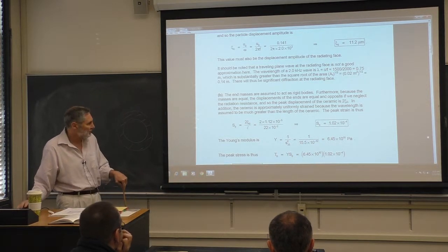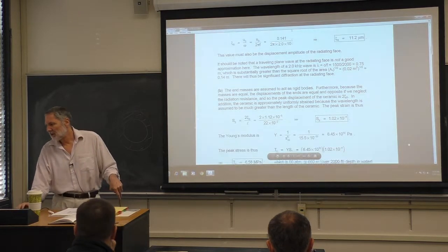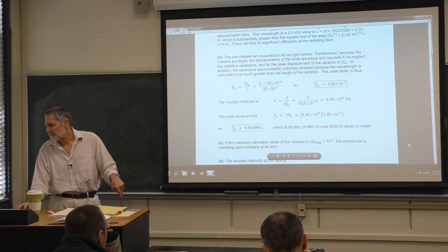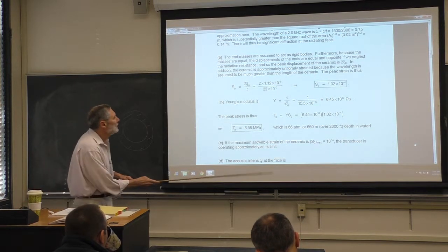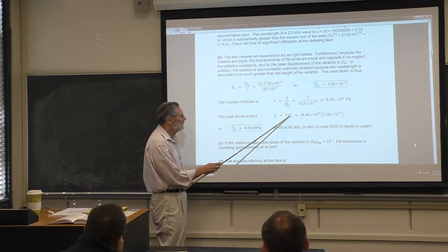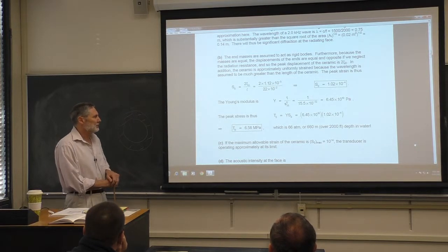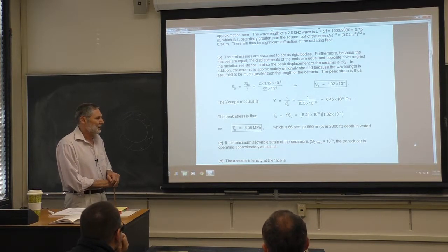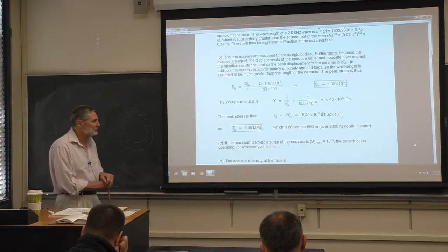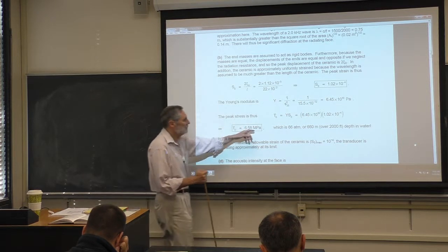The peak stress is going to be the modulus times the peak strain, and we get about 6.6 megapascals. I want to impress upon you that's a lot of stress, or pressure.